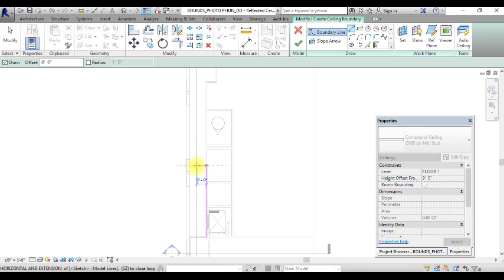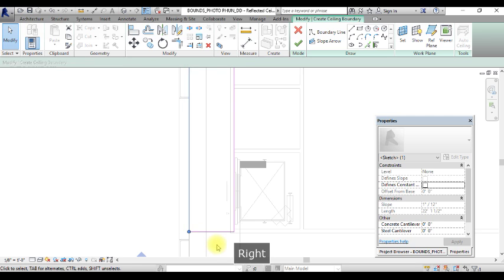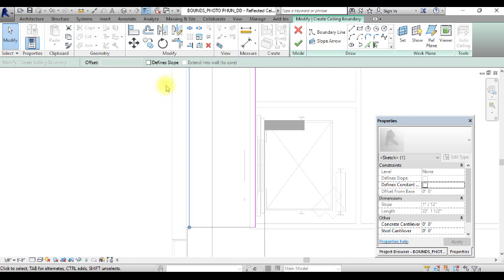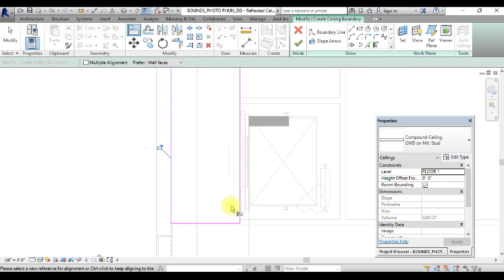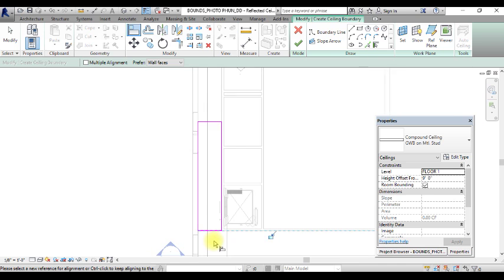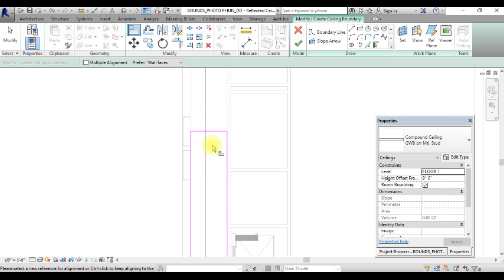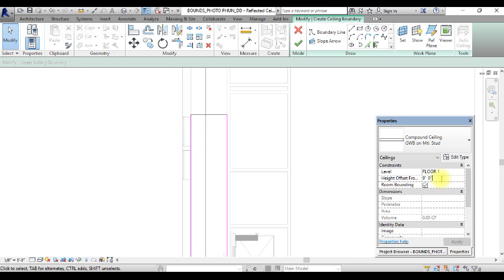I'm beginning to put in my first panel here, and this panel I'm going to set up to 10 feet. Now you can see I can use the align tool now. I haven't exactly gotten it drawn in there well. When we're working on laptops, sometimes it's hard to see, but go back and get your lines precise where your ceiling ends exactly with the wall. Otherwise, you're not going to see a good seam there. And we can lock these into place if the area is important to us. Later I'll show you how we're going to be able to see the doors and what's happening below. But this is just a first guess at it.